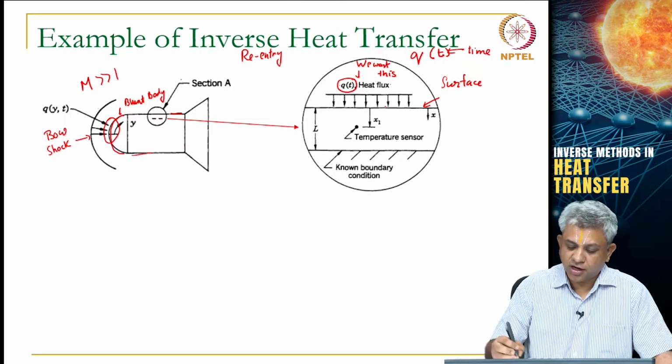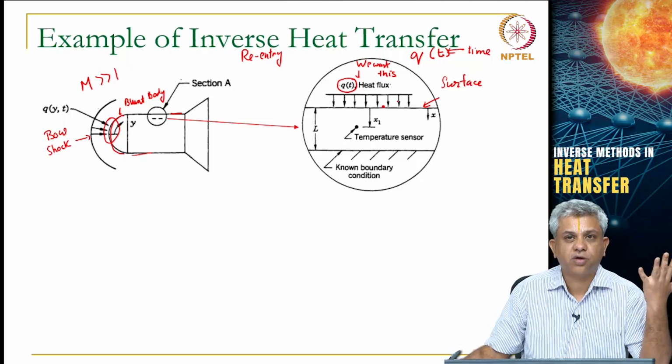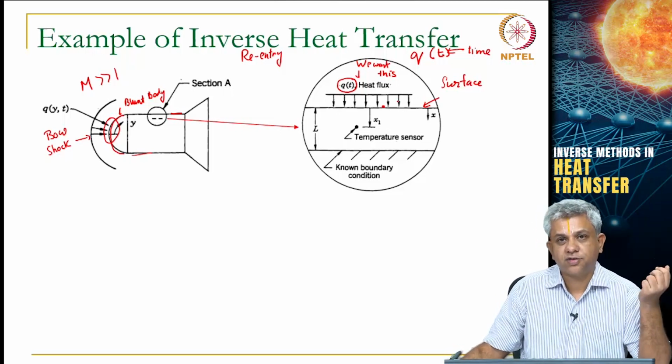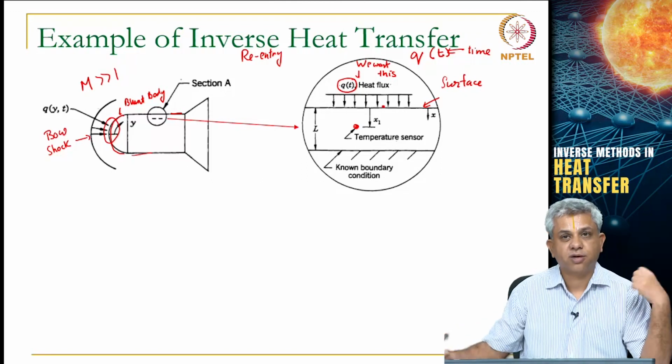Now, let us say NASA wanted to measure this. The point is you can't keep a thermocouple here, obviously not, the heat transfer load is just too high, no material is going to withstand that. So, what you do is you bury it within, you keep it somewhere inside.